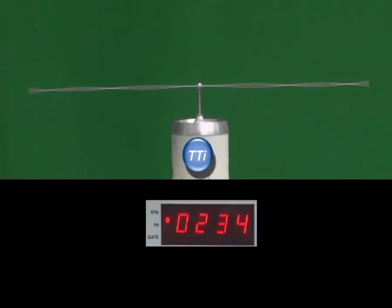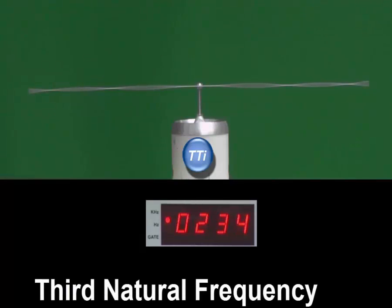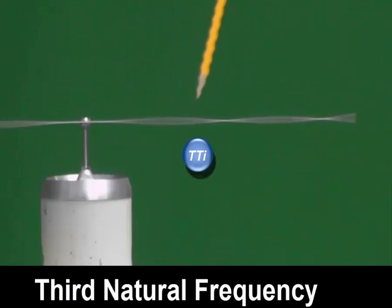I've now moved the frequency of excitation up to 234 Hertz. This is now the next natural frequency, the third natural frequency. If we look at the mode shape, we can see no motion here. At this point here, we've got large motion. We have a node here, no displacement, more displacement here, a second node at this point, and then motion at the end.